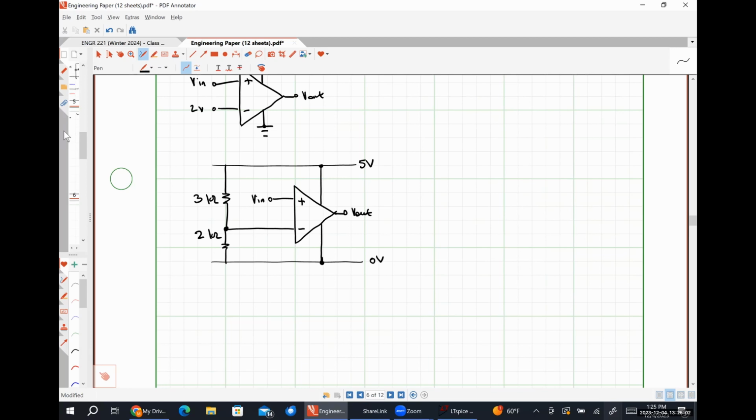So this is going to look like 10 thirds, 10 thirds, 10 thirds. So we're going to have 10 thirds plus 10, which is 40 over 3, in parallel with 40 over 3, which looks like 20 over 3. 20 over 3 plus 10 over 3 looks like 30 over 3, or 10.